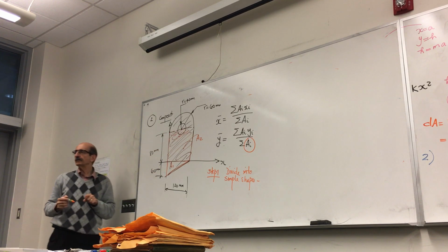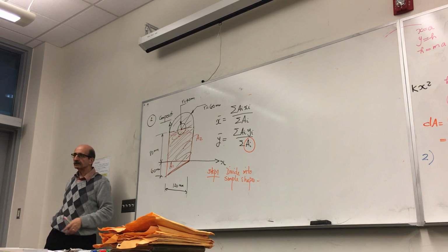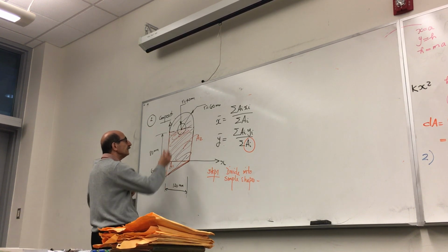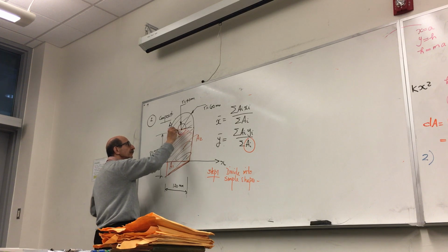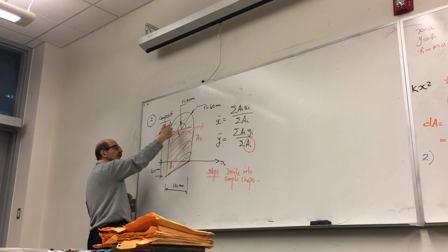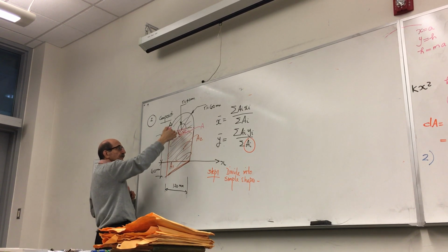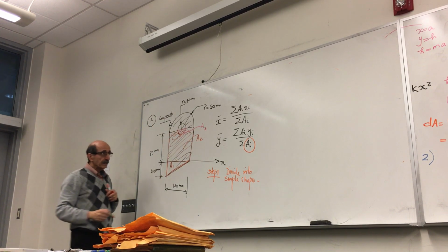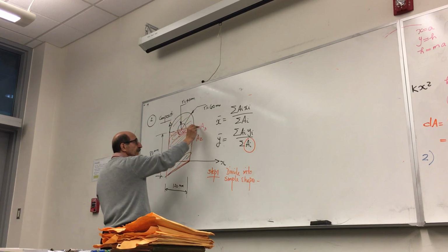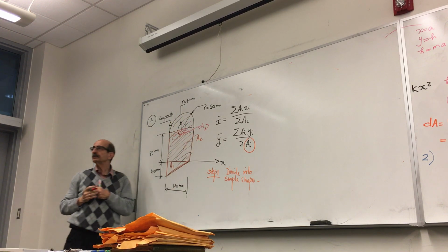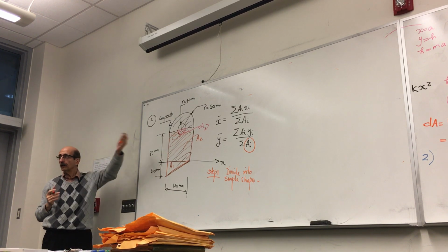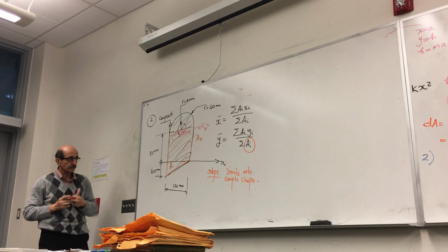And if I have a solid shape, that some piece is cut out of that, which is another simple shape, I would consider that to be a negative area. So from this rectangle, I mean this rectangle doesn't exist because this piece has been cut out. I call this A3, and as you see later, to differentiate that with the other values, I put a bracket on these two sides, meaning this has a negative value. In all operations, I consider that as a negative value.